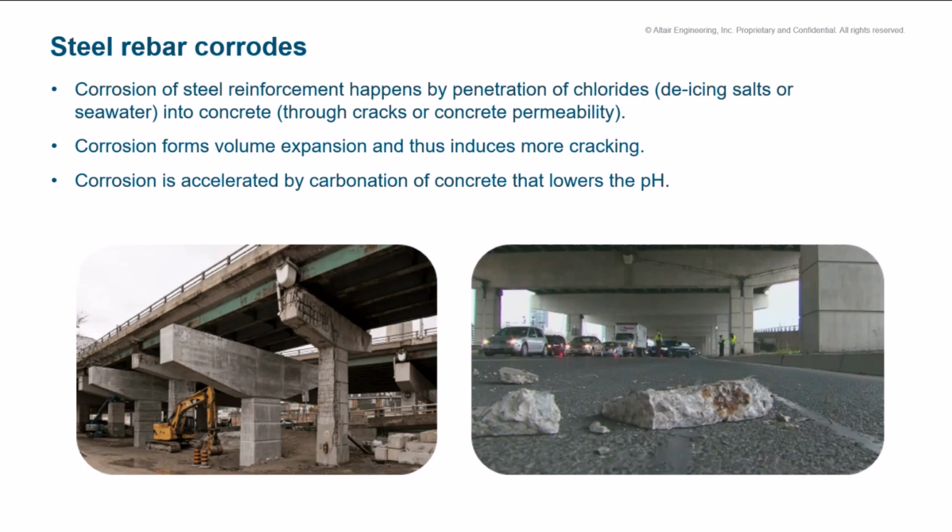Before that, I want to give a little background on this material and maybe some of the motivations for it from the design community. As we know, concrete spalls and deteriorates over time, but one of the primary reasons for that is that the reinforcement is steel, and that steel is subject to rusting and other types of corrosion. So what the GFRP product is trying to do is to reduce or eliminate that reaction between the concrete and the reinforcement. You'll probably see this as you're driving down the road, in any infrastructure project. It is most common in roads and bridges, not so much in buildings, but exposed concrete buildings could also have issues with this, as well as issues with cracking.